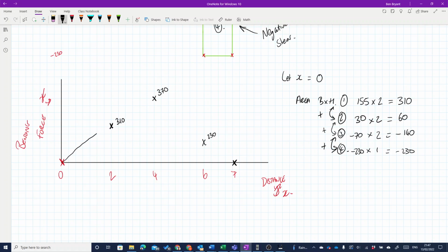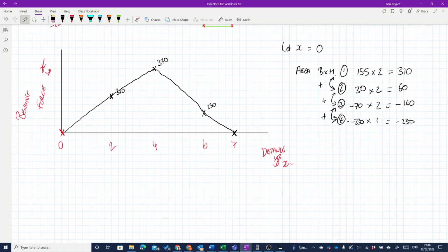If you try and run a line of best fit, hopefully you draw better than me. Run it up, down, down, and down. That's our bending moment diagram. Currently we're showing moments positive anti-clockwise, which is why it's given us a positive region or zone. If you did moments as clockwise, which is negative, obviously it would drop into a sag or a negative, so basically put everything down.